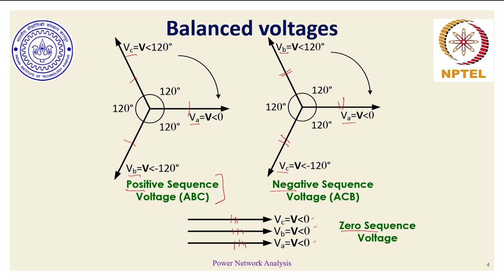So that is the important part: for a three-phase system, there can be three definitions of balanced voltage. Now the question is, fine, three sets of balanced voltages are possible in a three-phase system. Which one of them actually exists in practice? The answer is simple. In practice, by design of alternators or synchronous generators, our machines tend to generate positive sequence voltages, and consequently our loads and transmission lines also experience this positive sequence voltage. That's inherently by design. Someday if the orientation of positive sequence reverses to negative sequence, that day the negative sequence voltage would become the convention for generation, transmission, and distribution.